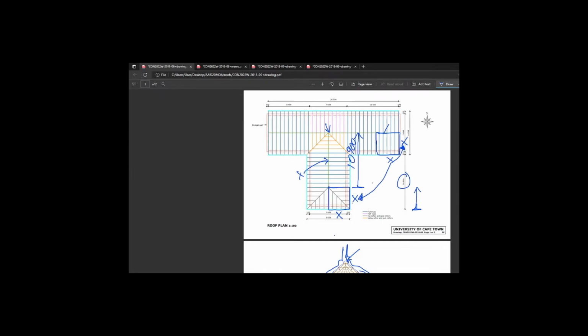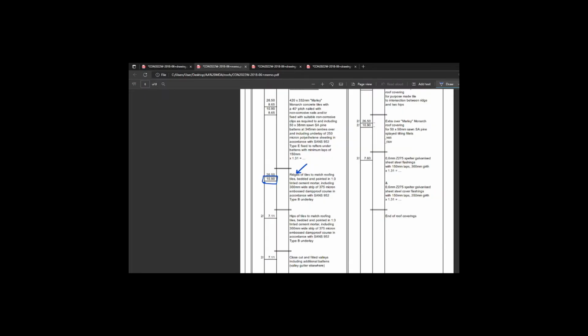And they're exactly the same because it's a 45, it's going to intersect halfway with this width. Right? And because it's halfway, and this ridge, which is not a ridge, it's just a ridge in inverted commas, apex, is also in the center line, that is the same. And because we moved by x this way, it must move by x that way, and we can take 10.9 as it is, and we add it in linear meters of ridge tile.